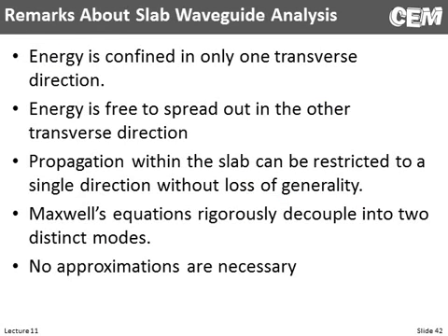Some final remarks about slab waveguides. For slab waveguides, energy is confined along one dimension and free to do whatever it wants to in the other 2. So we notice we restricted propagation to the z direction in the slab waveguide. But if you imagine rotating the slab waveguide, after you rotate it, if all those layers are of infinite extent, it still looks the same. So in fact, we can analyze a slab in the z direction, and those results apply to any direction.